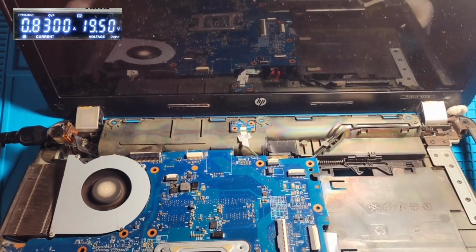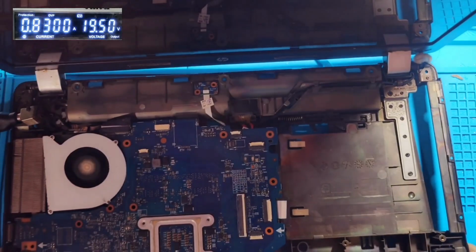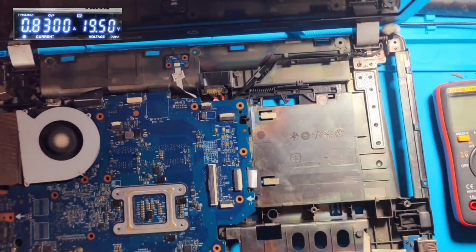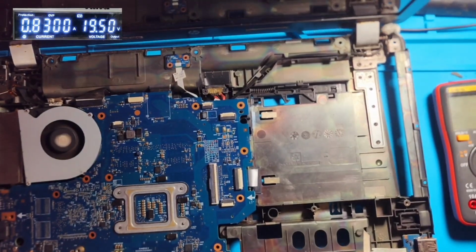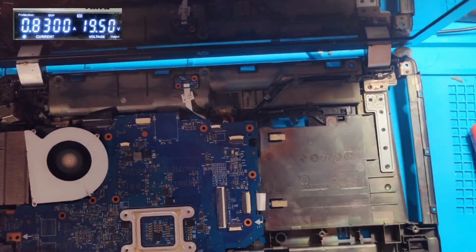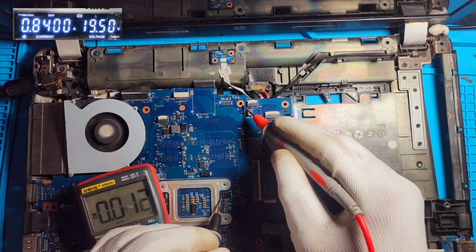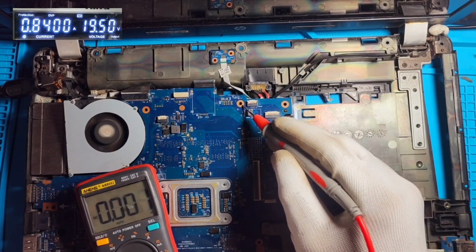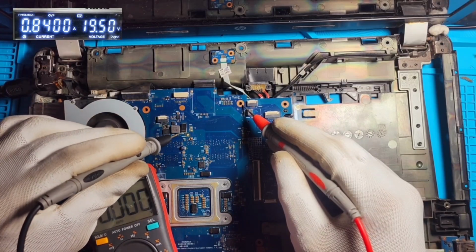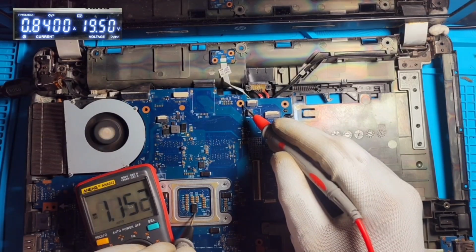But right now we have got the voltages of the CPU, I guess, because at this type of current consumption we should have got the voltages for the CPU. So there is something that is making the CPU not execute the display. So we have to check that. Okay, I am getting something. So the RAM voltage is present. Yes, 1.5 volt. And also the CPU voltage is present.